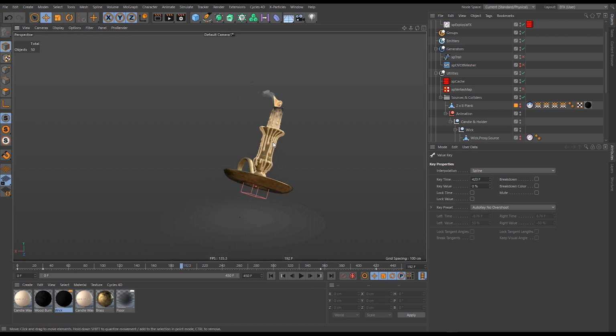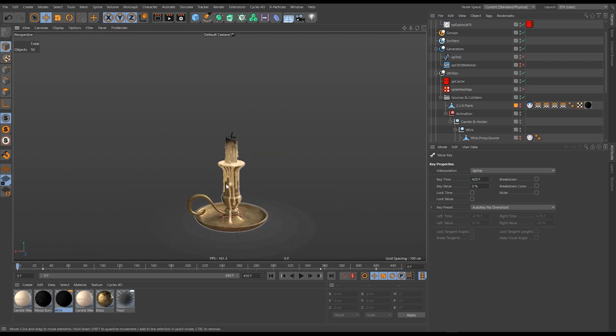Okay, so that completes our candle flame and wispy smoke project. We've learned there how to create source geometry out of a more complicated mesh, and also the same with some colliders. We've learned how to shape a flame to make it look like a candle flame, especially using our diffusion and dissipation settings. And we've learned how to balance our fuel and heat with our burning model and our ignition temperature to create that wispy smoke. And then we've taken that resulting simulation and had it transfer vertex weight to a piece of geometry to create a soot effect in the material. And then finally, we animated our candle, we animated our extinguishing, and then we cached the resulting simulation.